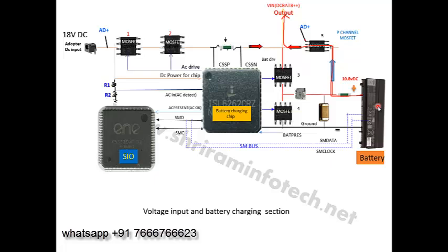Problem number 2: you have a laptop which is not working on the battery but works on the adapter. When I connect the adapter, it works fine and shows the battery 100% charged, but when I remove the adapter, the laptop turns off. Then there is a possibility that this MOSFET number 5 is open, and you have to replace this MOSFET. So this is problem number 2.